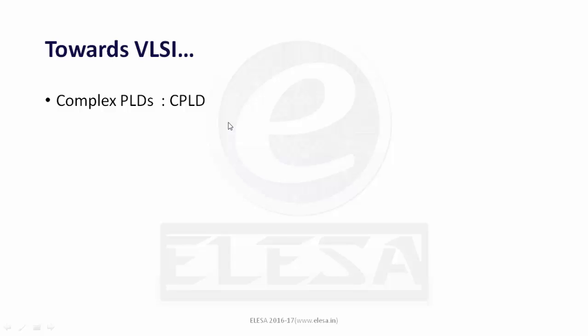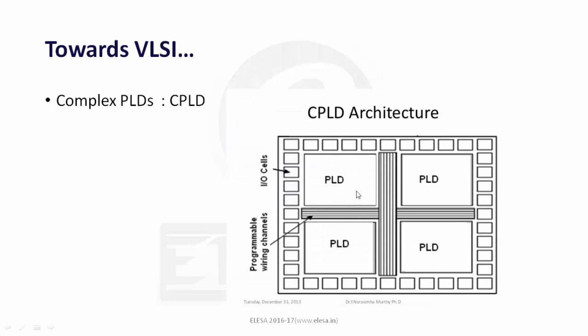So what is inside a CPLD? Now, CPLD actually consists of a number of PLDs in it. The PLD that we have seen was a single PLD, and it is programmable, as we have seen, with any AND gate or OR gate, but a CPLD allows you to connect any two PLDs, any three PLDs, or you can connect each and every PLD of the CPLD with each other.